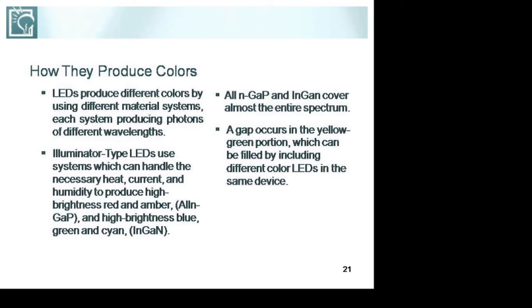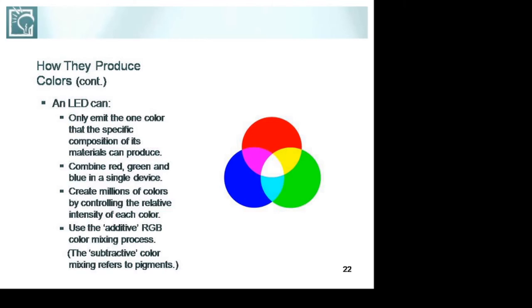The LED is made up of various semiconductor materials, like gallium phosphide and others. Based upon the materials added and the quantity of material added, a particular color will be exposed more, or the brightness will be reduced. If I want to use a particular LED to produce different colors, the same LED has to produce them based upon the supply voltage.